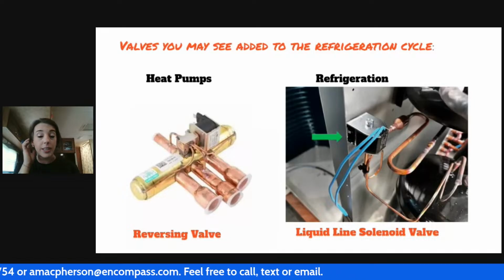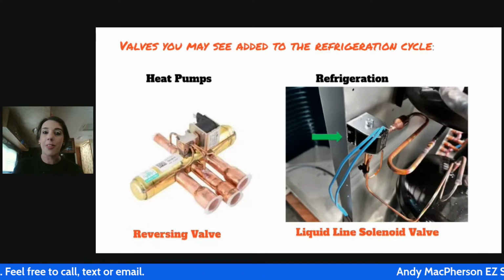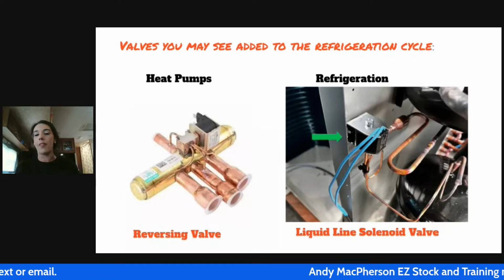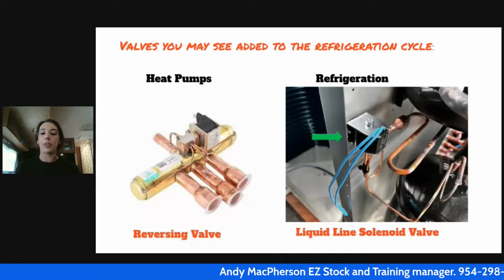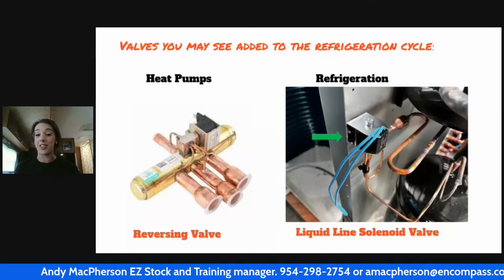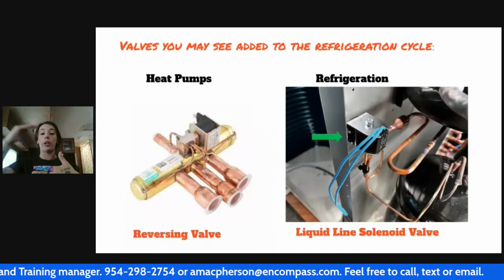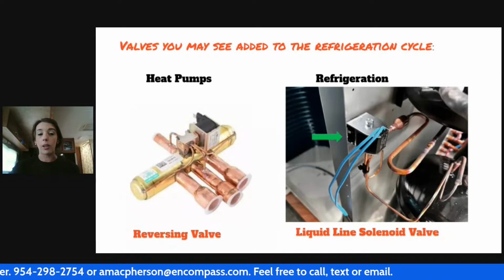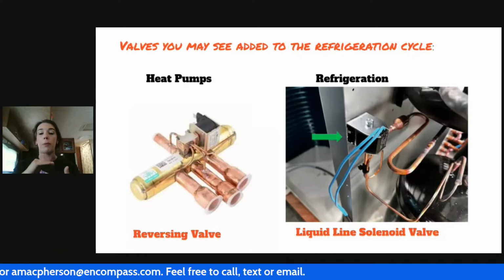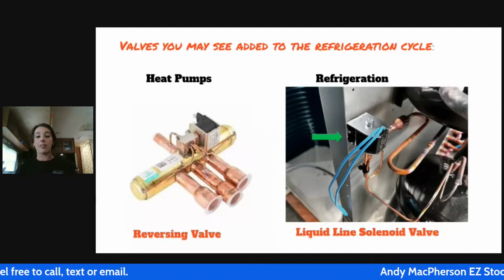Now, what's more likely going to happen is we're going to build up ice on the actual coil, on the fans, on the unit. And because the refrigerant is still sitting there, it's just going to make it colder. And we will have a hell of a time getting the ice off of that unit. When we have ice buildups between the coil loops, you end up breaking them. Those coil loops will spring leaks. The ice will build up between them and spread them apart. And in that case, we're just putting holes or cracks in those coil loops.